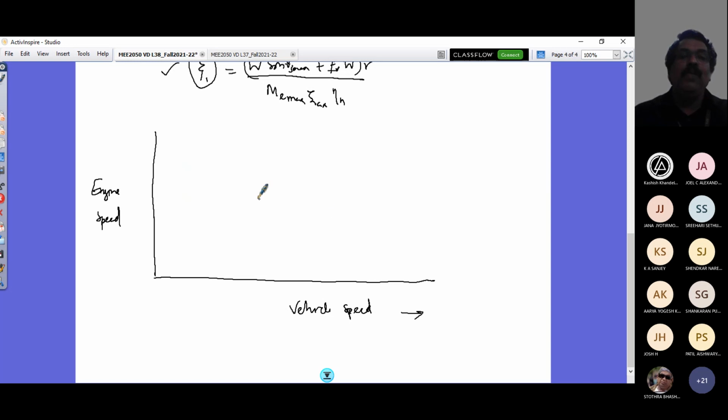So now we have got a maximum speed decided. So what I will do, I will take my maximum vehicle speed first on this horizontal axis. So that will be V4 in case of n equal to 4 gearbox. So for a 4-speed gearbox, I have my V4 obtained from my maximum vehicle speed expression.